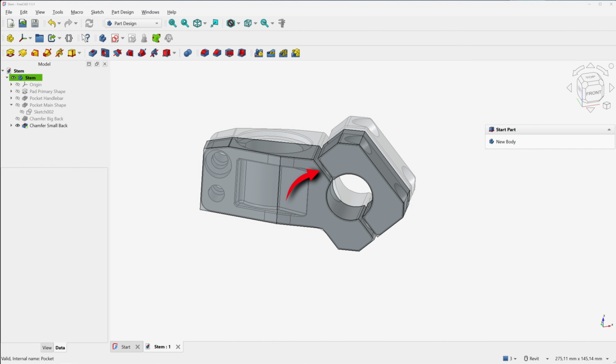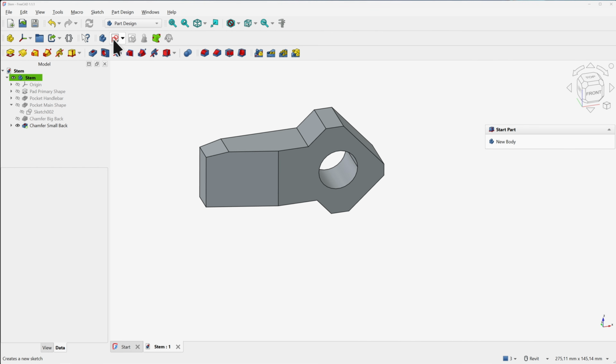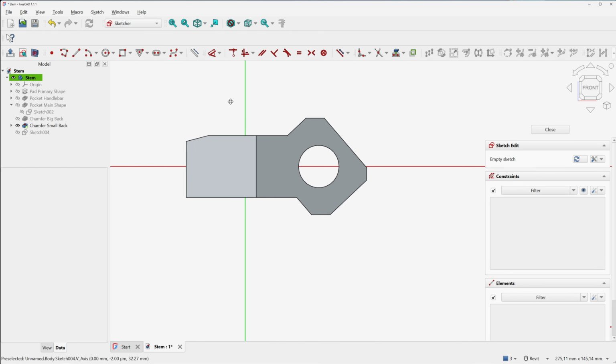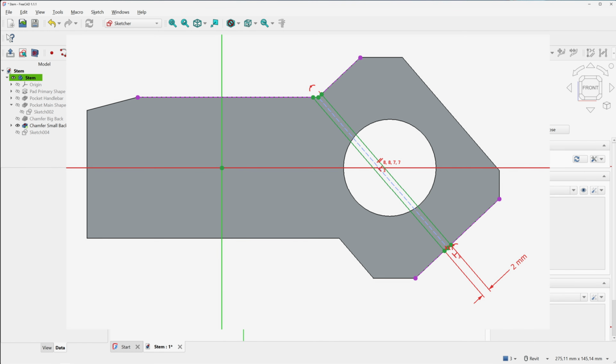For this split, we're going to leave a gap of several millimeters to ensure the bolts can be tightened properly. We're going to use the same pocket technique as before. To do that, let's start by creating a new sketch, and once again we'll choose the XZ plane. We'll also enable the section view so we can see through the model. The goal here is to recreate this sketch.